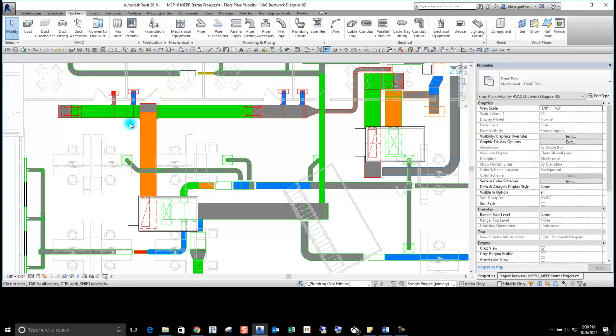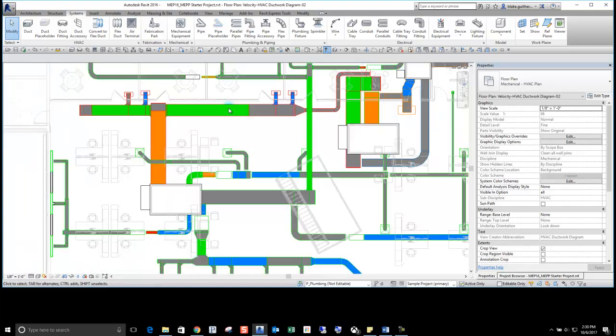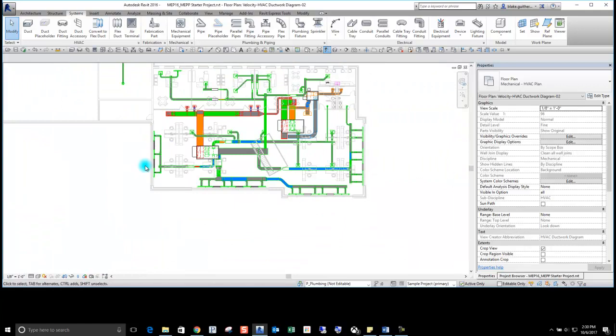There's a lot of firms out there that will design their fan systems and their ductwork systems off of block airflow, because the west zone of a building is going to peak at a different time than the east zone. So peak airflow would be adding up all the airflows and calling that your total. Block airflow says, hey, this box is going to peak at a different time than this box.